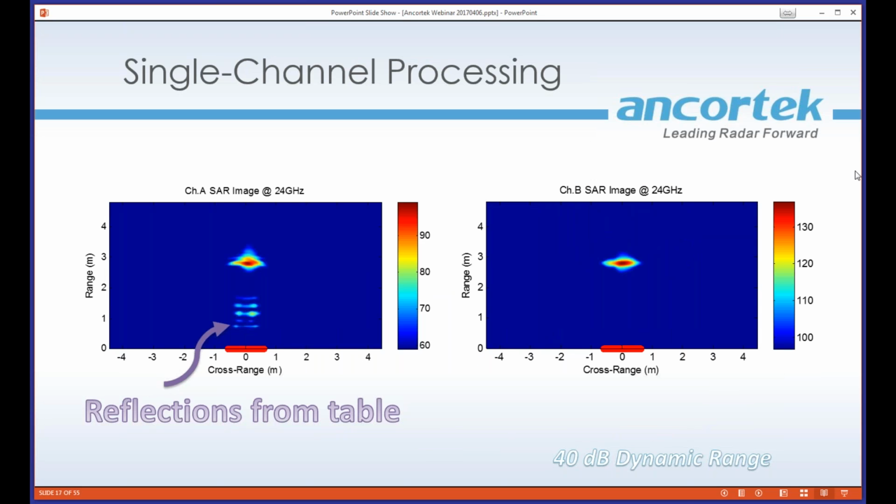Okay, so what we did was we went ahead and these are the DAS, or delay and sum, or back projection results. The difference is that our FFT images are just going to give us straight up FFT processing for range and straight up FFT processing for azimuth. Delay and sum goes through and tries to correlate in time the amplitude or the power of the signal that you received against the distance to each pixel. So for example, if I know that this pixel right here in the center where this target is, I can say, okay, if I want to add up all the energy that I got at all those different time instances from all of my different collections down below, it sums all of that up. That's the sum part of delay and sum.